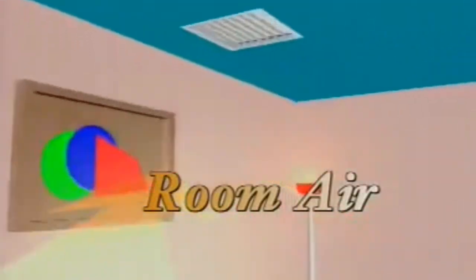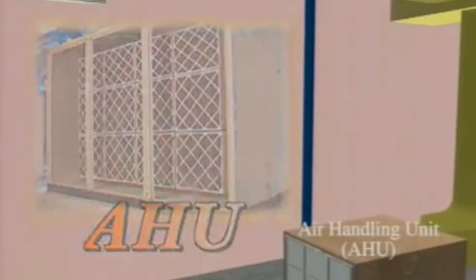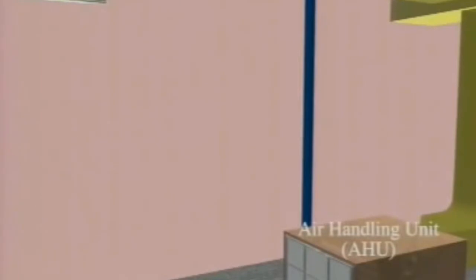Let us see how an air conditioning system maintains a cool and comfortable interior environment. In most central air conditioning systems, the room air is recirculated to the air handling unit, or AHU in short, via air duct. The room air is drawn into the AHU by the suction force produced by the fan inside the AHU. In the larger system, a separate return air fan may be installed in the return air duct to draw the air back to the AHU, where some outside air is introduced.